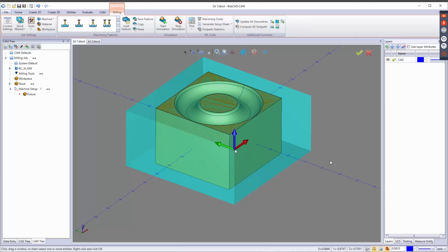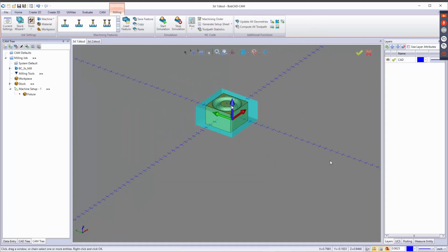If we move this gnomon from the corner here to the center, after we've got all our toolpaths in there, instead of going through each one of the geometries and selecting and reselecting, doing all that, we just say update all geometries and then compute all toolpaths, and it'll calculate it all the way through. We got wrapping groups, we got add new setups, indexes, toolpath patterns in here if we need to utilize those. Mostly indexing and wrapping is for 4-axis.